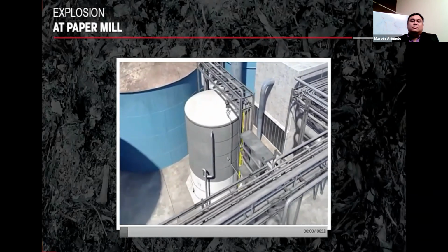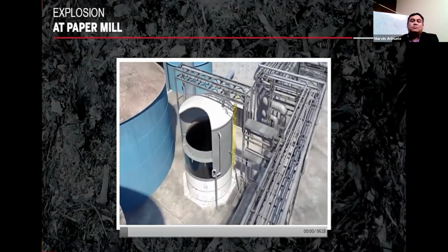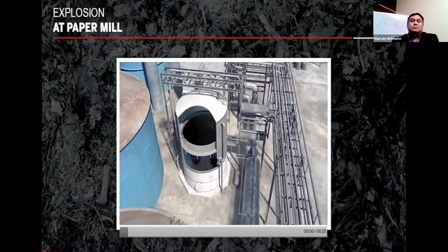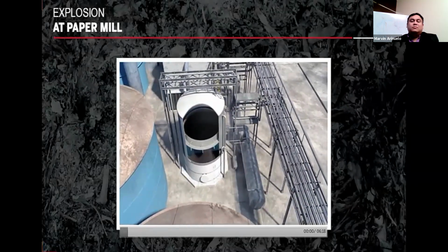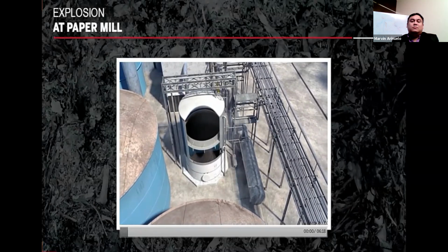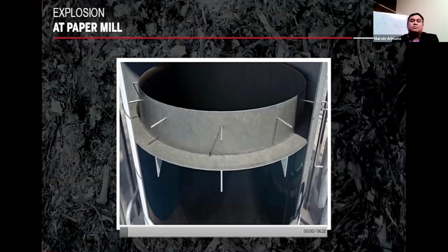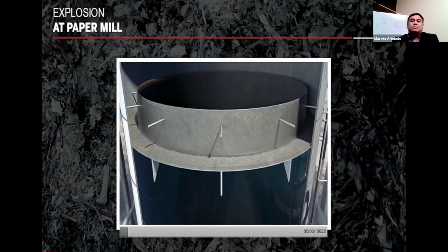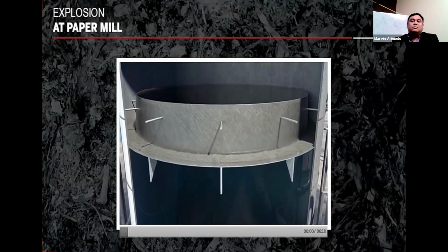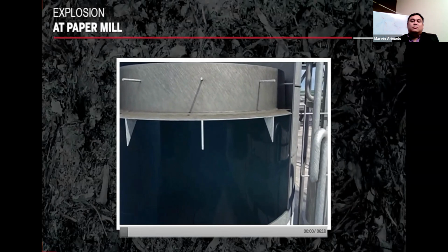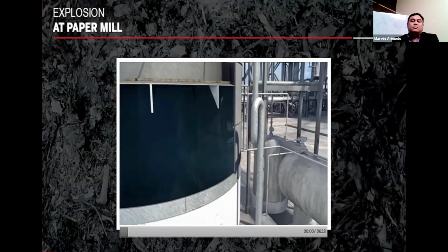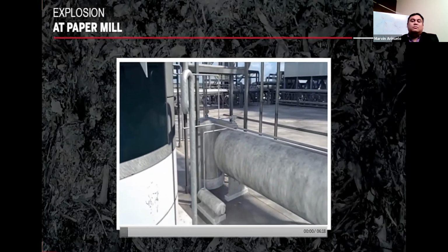These assumptions were, however, incorrect. Residual turpentine, normally present in foul condensate, collected on the top of the liquid in the tank due to its density. The foul condensate tank was designed so that by changing the height of the liquid level inside the tank, the residual turpentine would be skimmed off and sent to a turpentine recovery system.